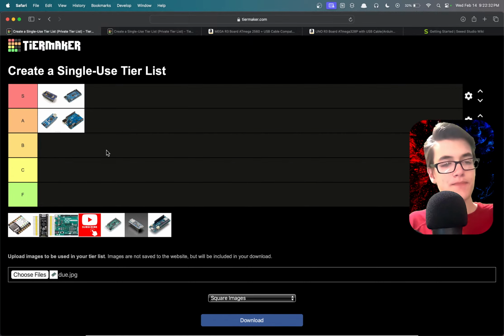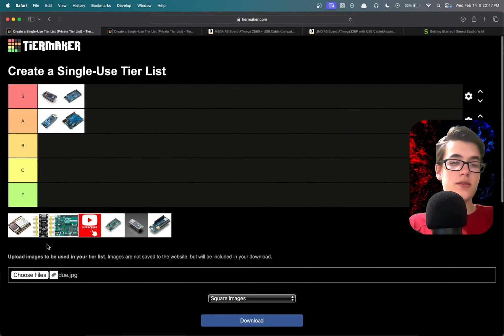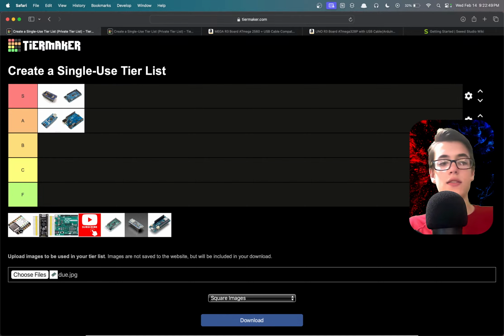But it does only run at 3.3 volts. That's a good thing to note. All of these that we've classified so far, I believe, run at the full 5 volts. So they can use all the devices because you can use 5 or 3.3. Some devices, like this board here, obviously you can plug 5 volts into the USB port, but they can only output 3.3 volts. So if you have one of those devices that needs a full 5 volts, you won't be able to run it with this. Like a relay, often the relays need 5 volts to toggle. You won't be able to swing that with this little board.